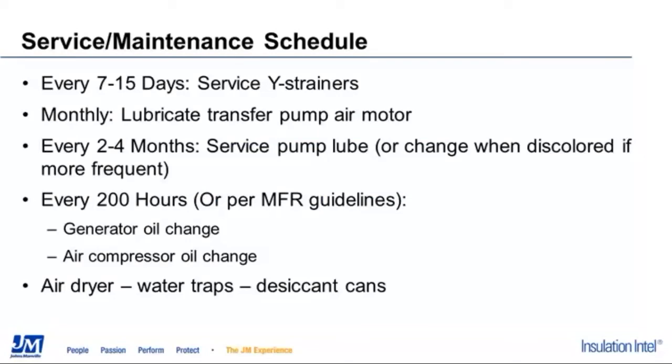But that Y strainer, and we'll look at a picture of it here in a moment, is something we want to be servicing every 7 to 15 days. So either every Monday or on the 1st and the 15th. And then I just want you guys to be aware that Graco, if we start digging into their manuals, would say that Y strainer is to be serviced daily. I'm not going to take away from that recommendation.